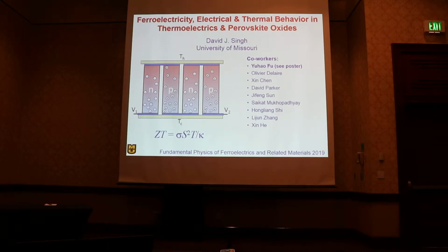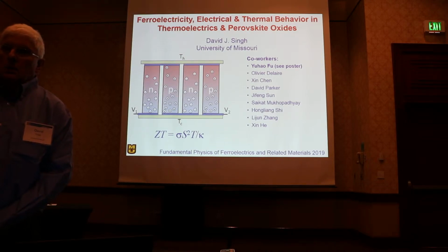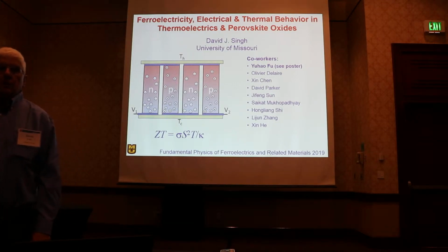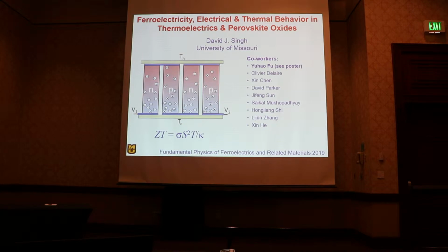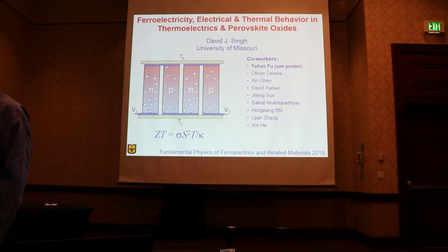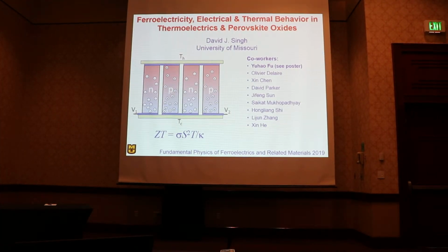And the way you can understand thermoelectrics is to think about the electrons in a semiconductor. So the electrons in a semiconductor, when you're at finite temperature, are excited away from the Fermi energy by something of the order of kT, and therefore they have entropy, which couples to heat gradient, and they also have electric charge, and that coupling between electric charge and electric field then means there's a coupling between electric field and thermal gradient,